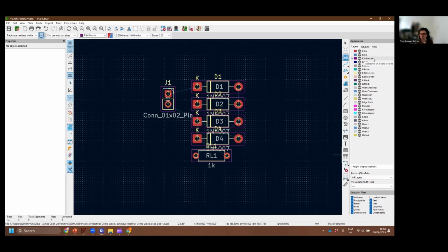So then after our copper layers, we've got a fair few layers that are mainly relevant if we're getting our PCBs manufactured. The two that are quite useful if we get them manufactured by someone like JLC are the silkscreen ones. So silkscreen's like a plastic overlay that goes on top of the copper and allows you to do things like printing annotations and stuff like that. So you can label the different components on your board with just some text. That all gets printed and it's usually a nice green with some text on it, and you can then more easily assemble your board because you can see where stuff's supposed to go and that sort of thing.